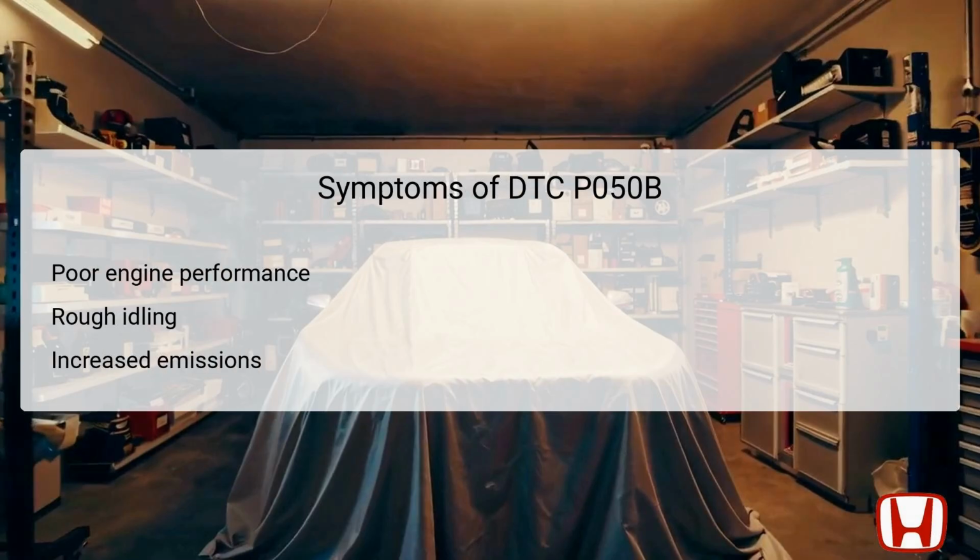The symptoms associated with DTC P050B primarily stem from its impact on engine performance, especially during a cold start. Drivers may notice poor engine performance, characterized by an inability to maintain stable RPMs or smooth acceleration. Rough idling is another common symptom, where the engine may shake or vibrate irregularly when at rest.